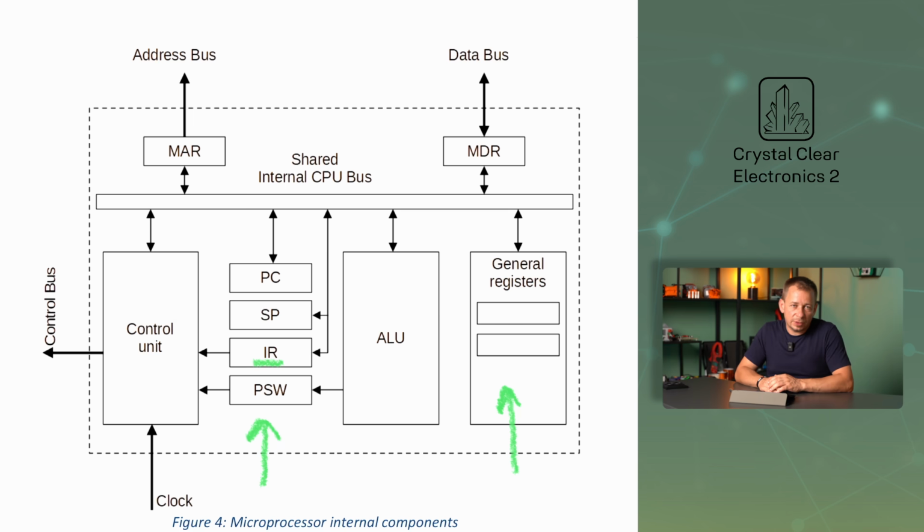The next register we will look at is the program counter, known as PC for short. The value of the program counter register contains the address of the next instruction to be executed in the program memory. Certain instructions, typically jump instructions, modify the value of this register to cause the program execution to jump to the correct location at every if-else branch. This depends only on the value of the PC register.